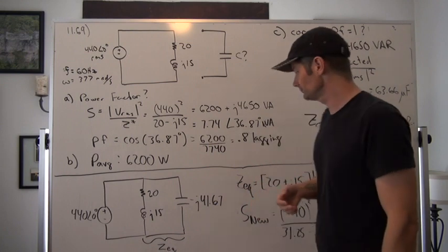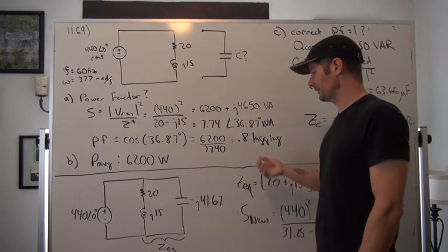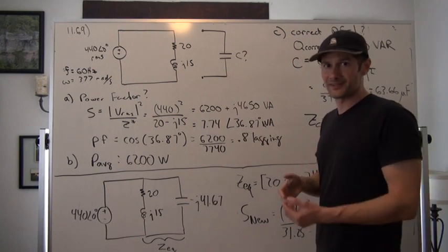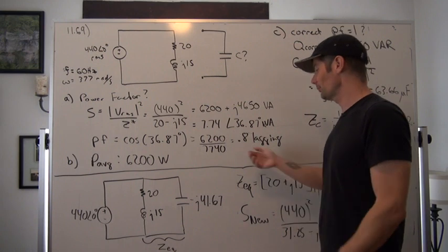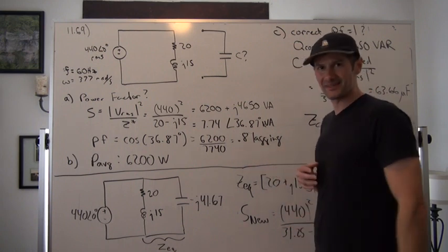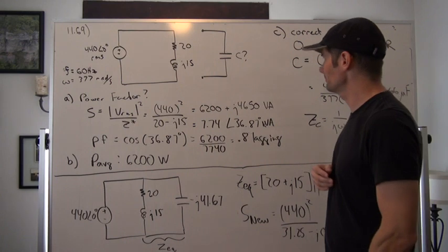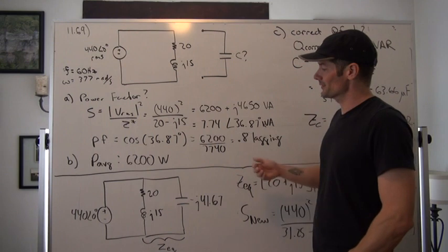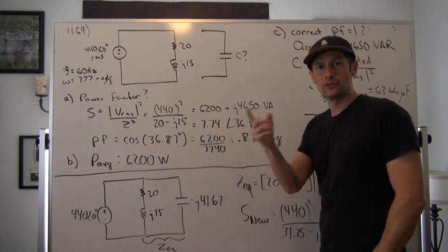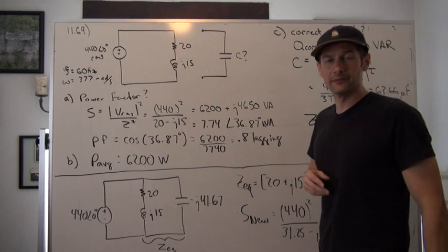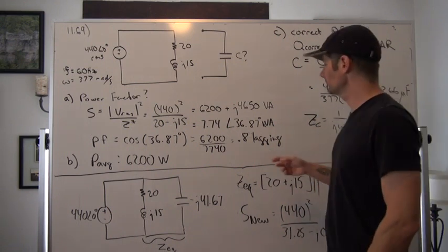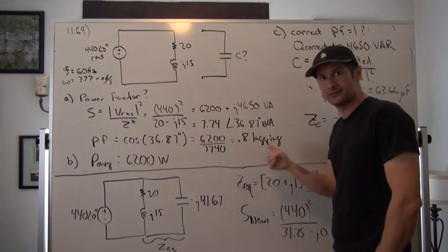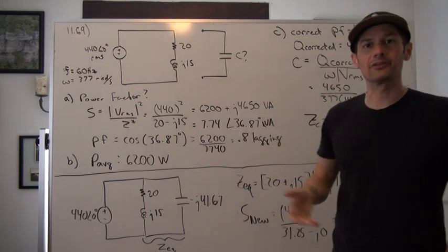And oof, guys, I know for some of you, you may be thinking, oh, 0.8 is not that bad. I mean, that's essentially a B on a test. But 0.8 is not good efficiency. That's pretty bad. In fact, if we look at this, that means we're only getting essentially 80% of that real power relative to the total amplitude of the instantaneous power being produced within the system. And obviously, because it was inductive, we say 0.8 lagging. If it was a capacitor, we'd say 0.8 leading.